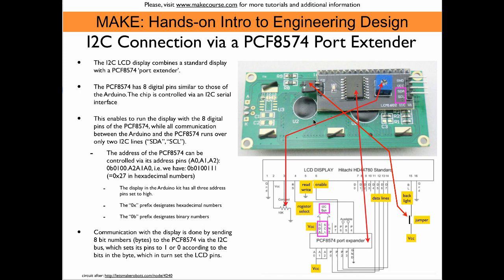Now in this particular case, all 3 pins appear to be connected to 5 volts, so the LCD display has the address 01001111 because these 3 pins are on 5 volts. Unfortunately, there is no way to change this without doing some soldering.